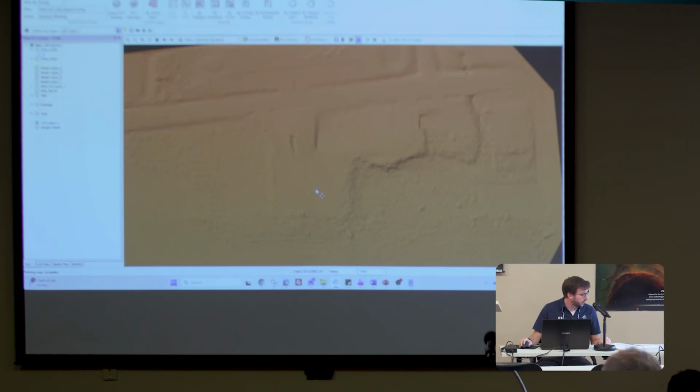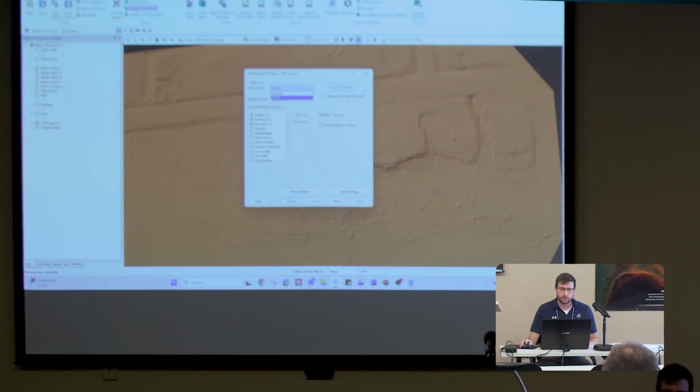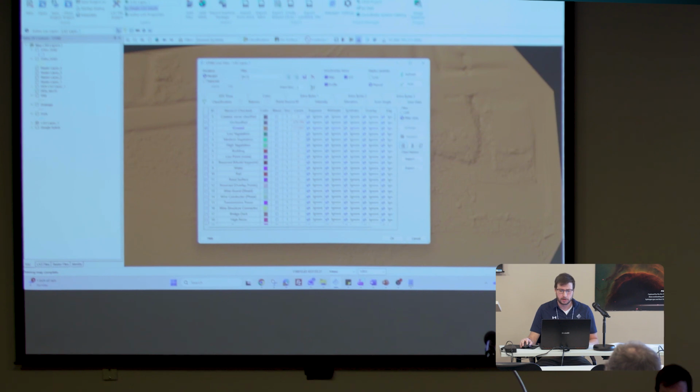So let's go ahead and, what we're going to do just to make this easier on us, let's go ahead and export a subset file, just to make sure that we have a low enough number of points to where we don't have any issues with this export. So go to project at the top, click export wizard, select for export types points, and export format LAS. Input points filter, change that to, double click in here in the ground row, click on model key point set.